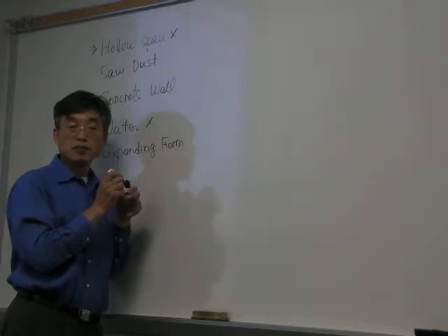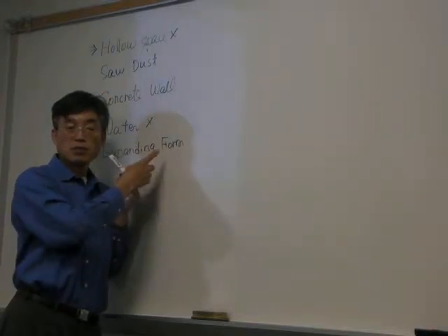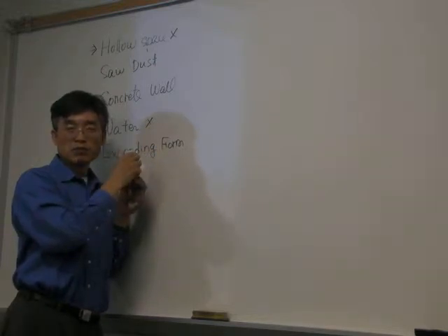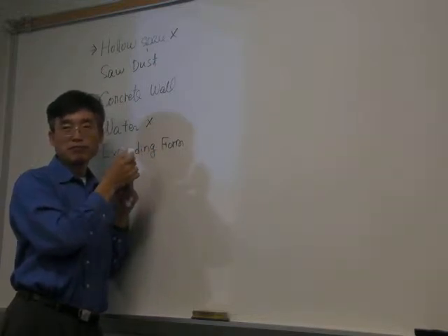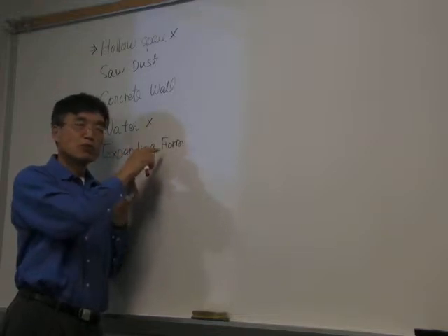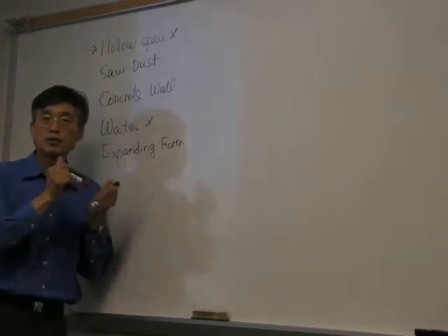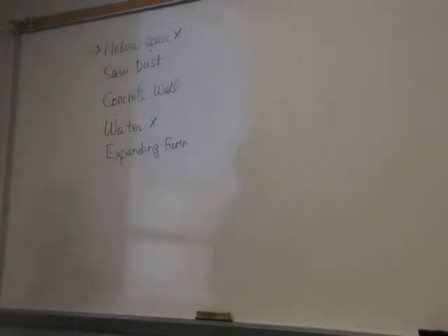The reason why people did not use this one is probably that this material is available maybe only recently. And another problem could be the cost. It would be kind of expensive, but not if it's closed cell. You have open cell foam and closed cell foam. Open cell can allow water in. Closed cell does not. Closed cell is really expensive.